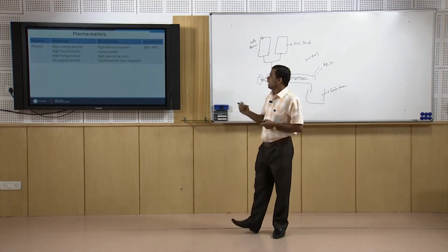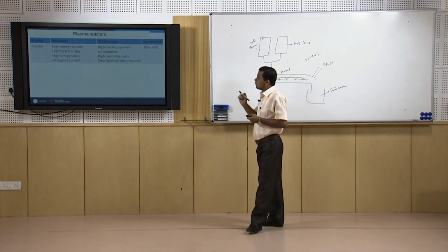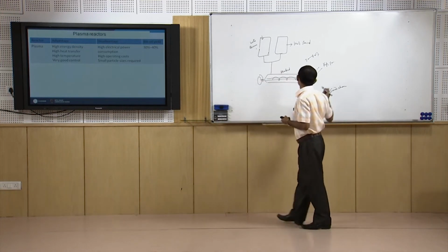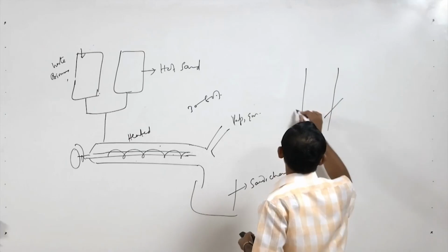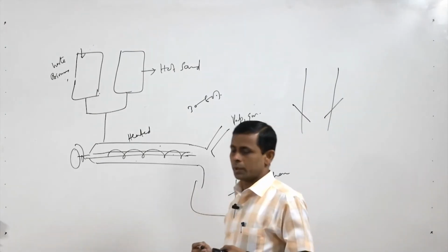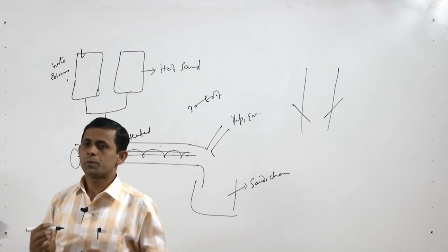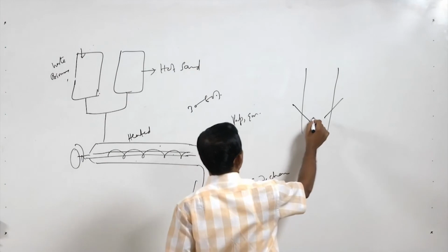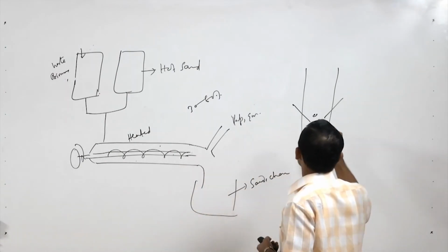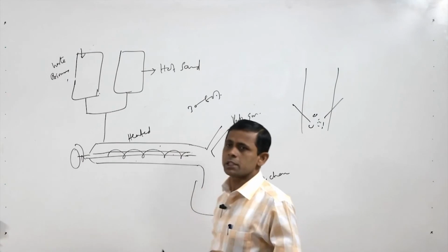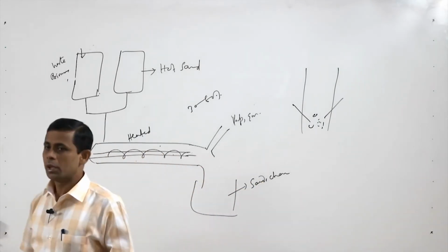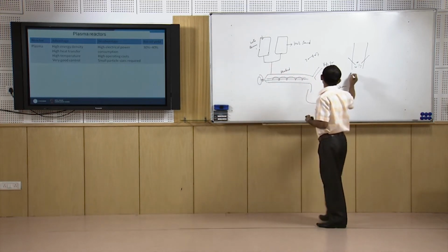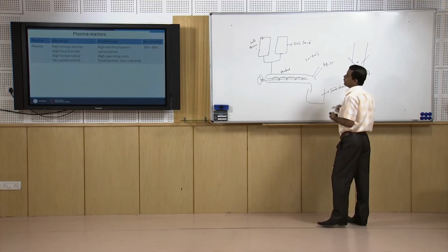In this case the condition will be different: plasma will be produced in the reactor, just like in a plasma gasifier, by applying high voltage across two electrodes, and under certain conditions the plasma will help to vaporize the waste and biomass inside. So, the vapor will form, which can be condensed further and then bio-oil can be produced. This is the mechanism for plasma reactors, and 30 to 40% bio-oil can be produced from this reactor.